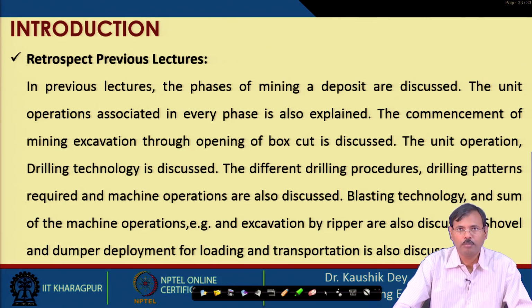We have covered the blast free excavation technology, that is excavation of loose rock mass using ripper, and the material handling technology using excavator and dumper combinations in shovel dumper combination system for the fragmented blasted rock mass. And we are continuing now with excavation with surface miner, which is also a blast free mining technology. We have covered already 2 lectures on this, and we are continuing with the third lecture. There will be 2 more lectures after this on the surface miner technology.